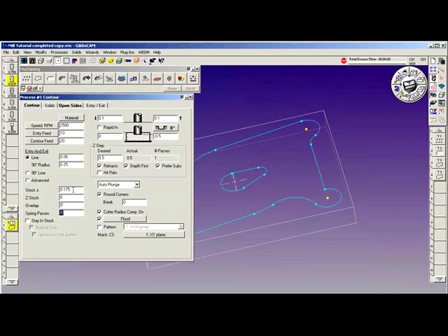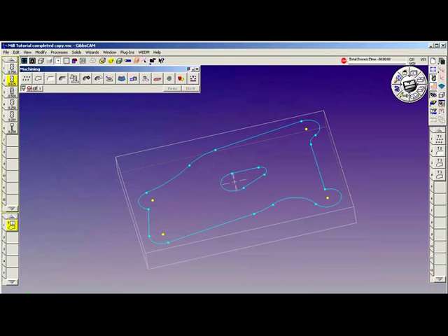We'll go with these same values here, 0.1, 0, 0.1, minus 0.5, and we're going to split this into 2 passes also. We're cutting around the outside in 2 passes, auto plunge, round corners, 0 corner break, and once again, flood coolant is on. We'll close the dialog, and then we're going to stage our finish tool. Finish tool is going to be tool number 3.